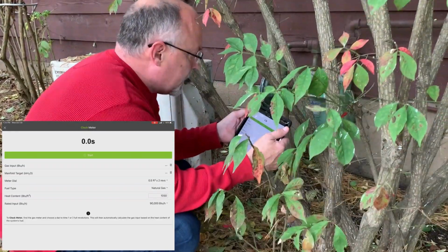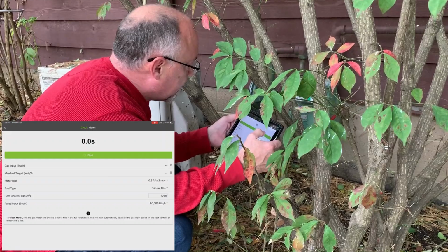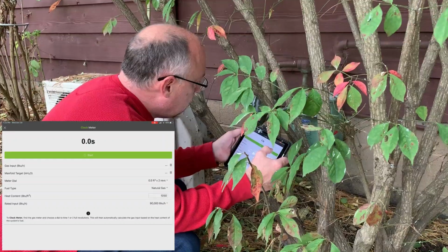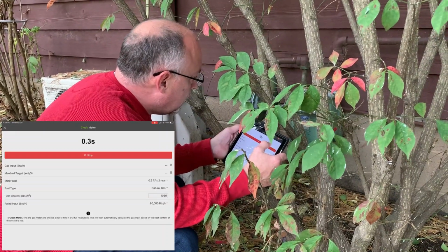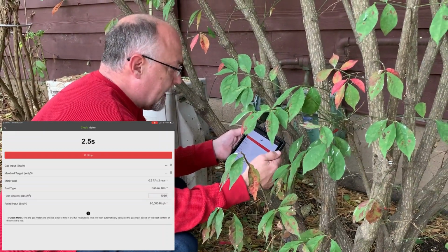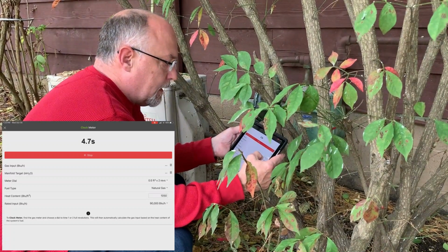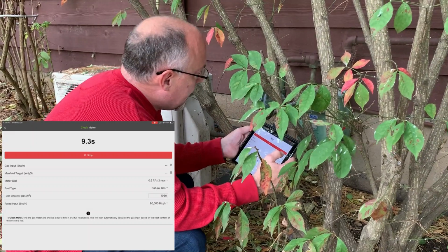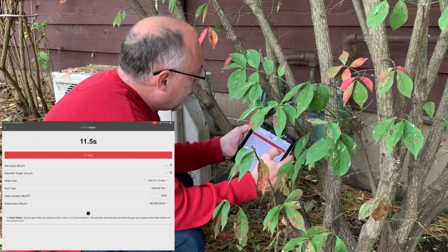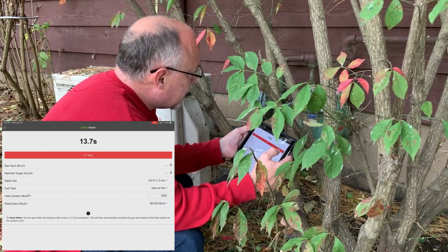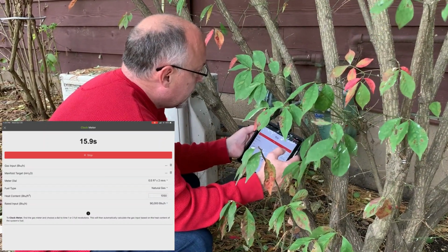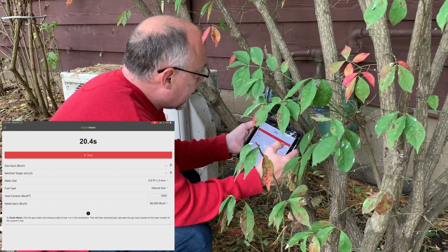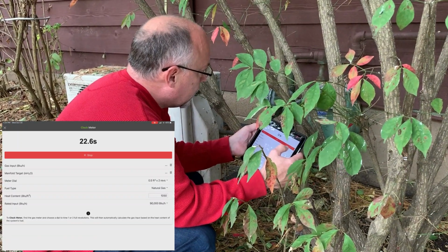All right, so we're going to watch the half cubic foot dial. I'm going to wait till it gets up to the top here. And I'm going to go ahead and hit start right now. And we're going to let that go around 2 times. I have this set for meter dial, half foot, 2 revolutions on there. And we'll get a clock input on here. I set this up last year, so the meter should not drift, or the gas pressure should not drift, so it should still be pretty spot on. That's the first one. And we're coming around for the second one.